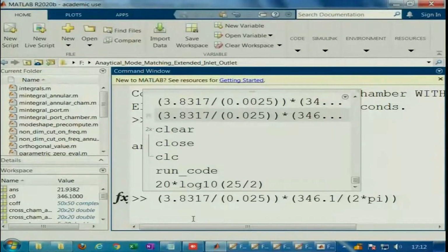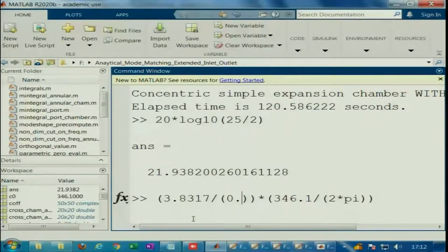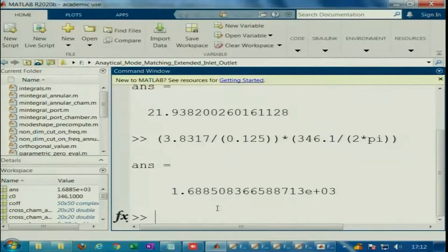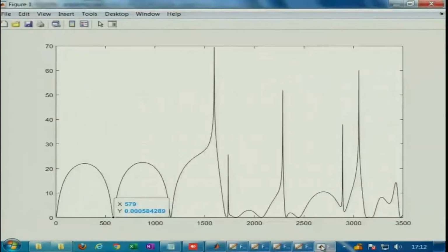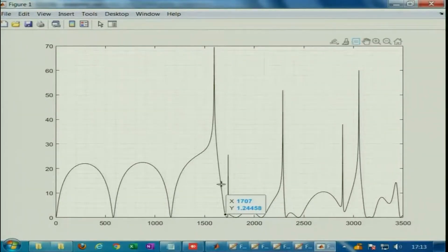And what about the radial frequency now? This becomes 125. So, 1688 is where we get the first one, at this frequency 1688 we should definitely get a peak, near trough near about that 1688. So, if we just go a bit back, 1688. So, there is a modal coupling involved. So, we are definitely going down, and a trough occurs just immediately afterwards at 1718, very close. It is characterized by a huge spike.